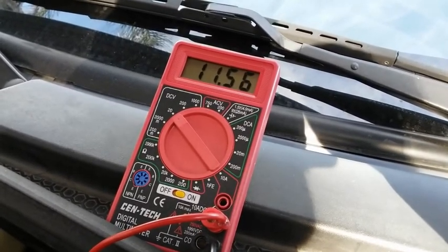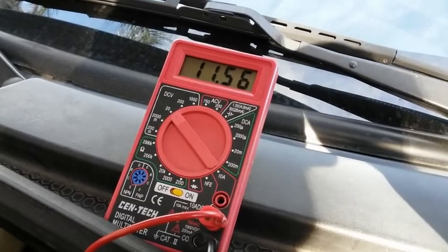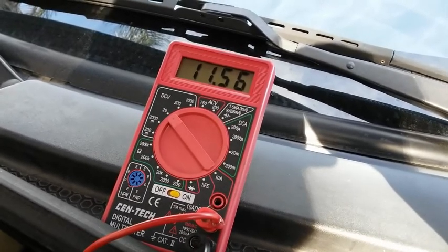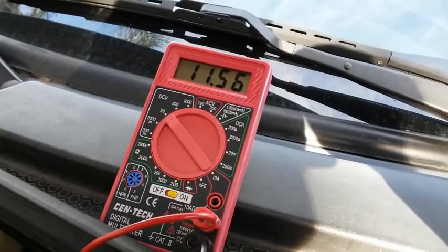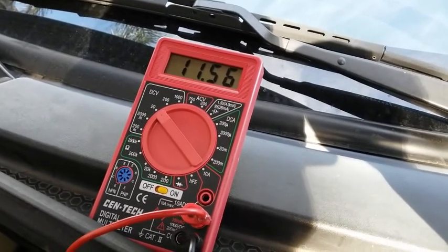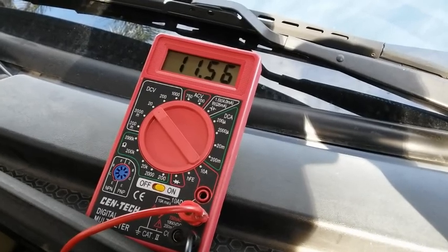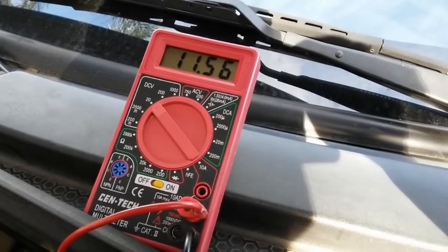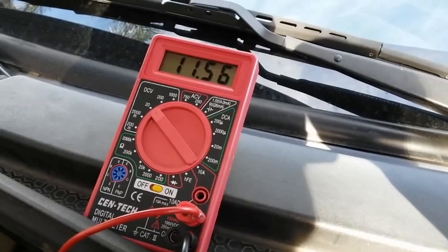That's the condition on a pull down design: with the connector connected, key on, engine off, our voltage should be approximately 0 volts on the signal wire, and once you unplug it, it should jump to approximately battery voltage. In this case, this happened.